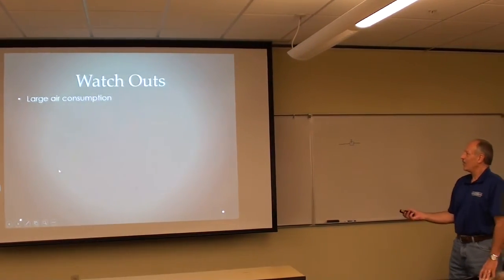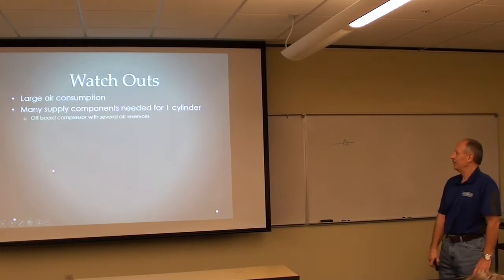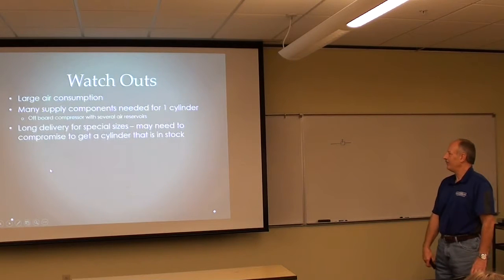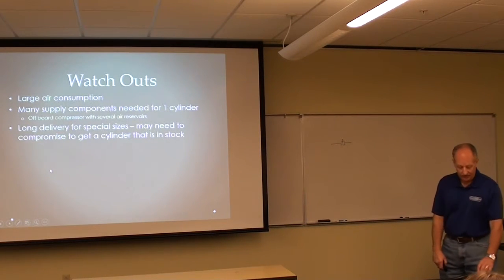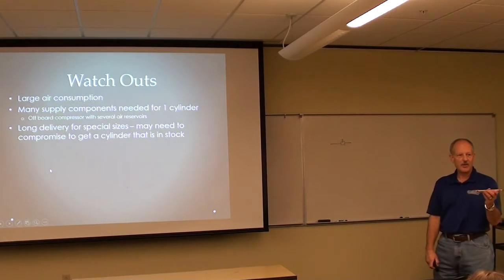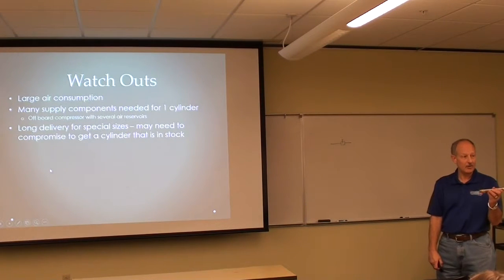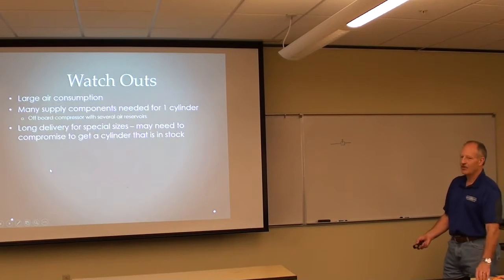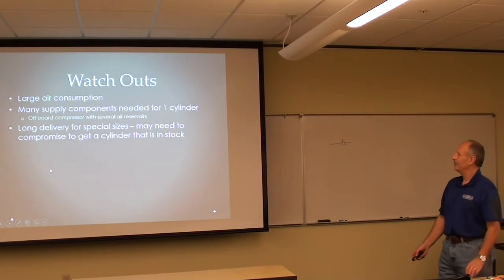Other thing to watch out for, large air consumption. So we talked about that. Also long delivery time. If you special order cylinders, they can be much longer than 6 weeks. So you always want to look for cylinders that are stock.